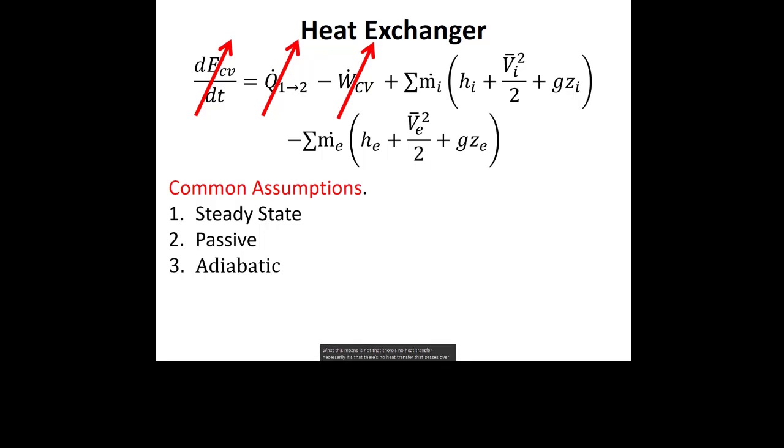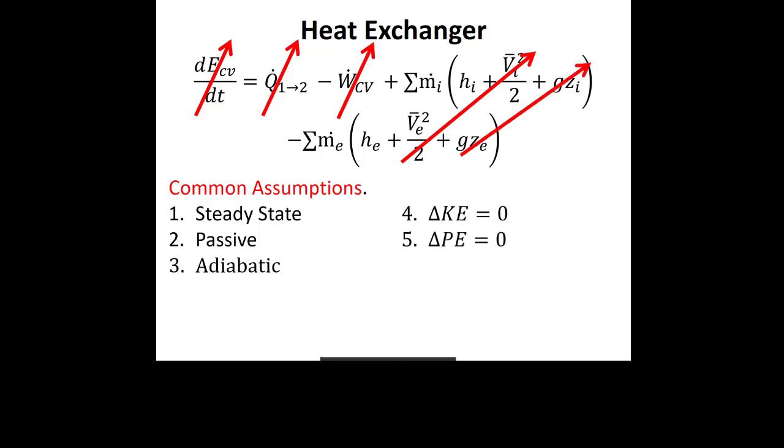So if we draw our control volume big enough, all the heat that left that engine oil is going into the water. But if we look at the control volume a little bit differently, then this Q dot term might stick around. So we'll definitely do some examples of heat exchangers, and I'll show you the different ways you can work on them. Right? We're still going to neglect kinetic and potential energy. This is good, right? Because in most of the components we've looked at, the kinetic and potential energy terms drop out, and those are the ones where the units are the most difficult.